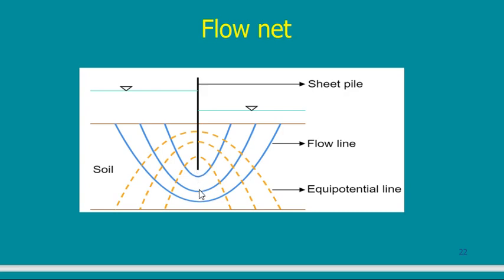The next one, you should make it a little bit bigger. The next one should not be here. It should be more than that, because it should be a little bit bigger. Say between you and me, if this is 4 millimeters, the next one make it 6 millimeters, the next one make it 8 millimeters, and so on. This will give you a good shape for the flow lines.